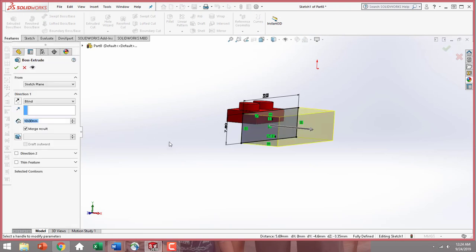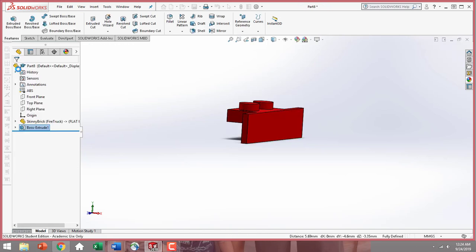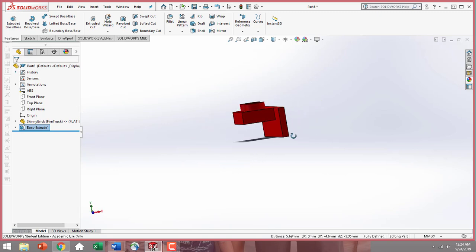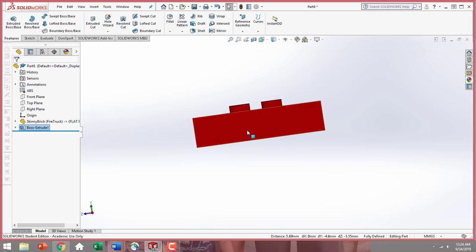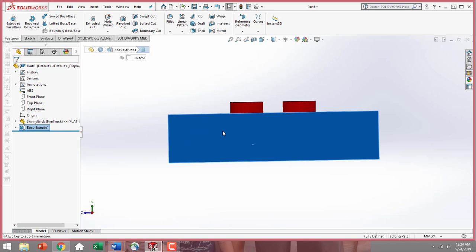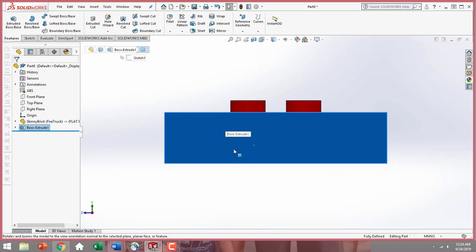This is a thinner extrude. So once again, you're going to want to measure that. It's about 1.5 and hit OK. So we have our basic brick right now. Go ahead and select that face and bring it normal to.